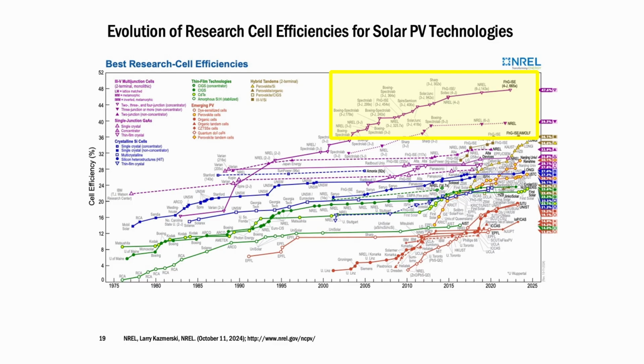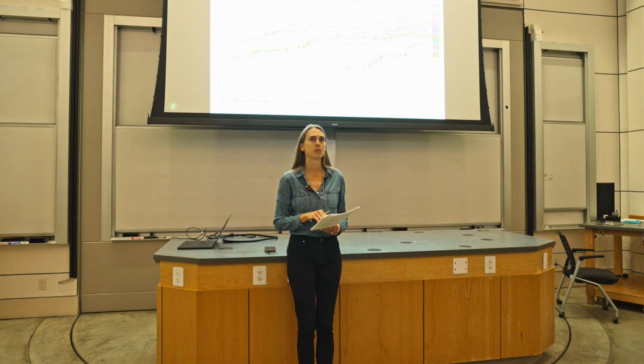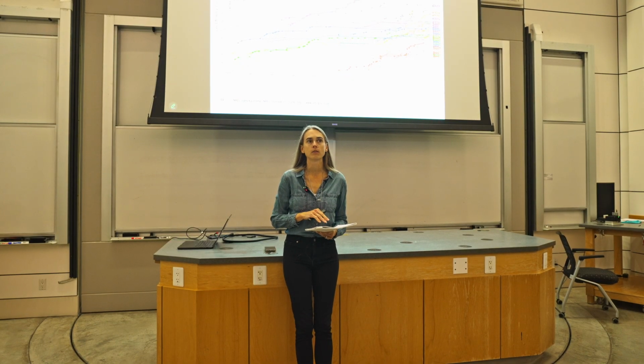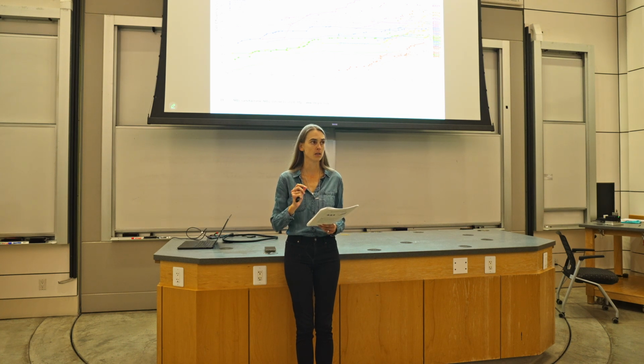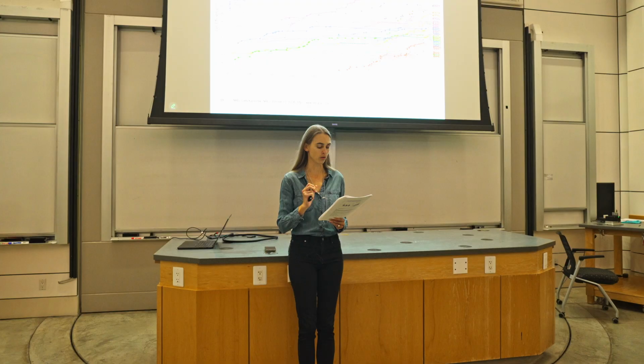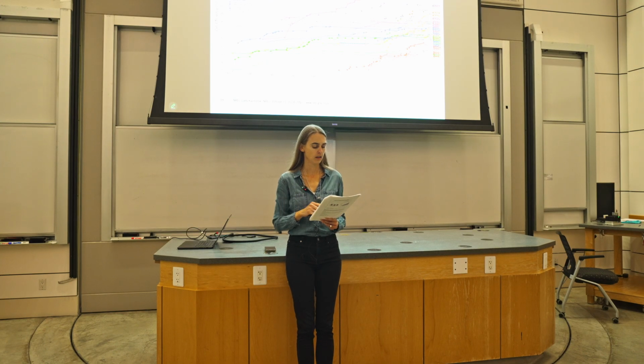These are the multi-junction cells that are made up of multiple types of semiconductor materials stacked on top of each other, each with their own PN junction. So that's why they're called multi-junction. A little bit of context on multi-junction cells. Different semiconductor materials have different band gaps, which is the minimum amount of energy required to knock the spare electron loose from its bound state.